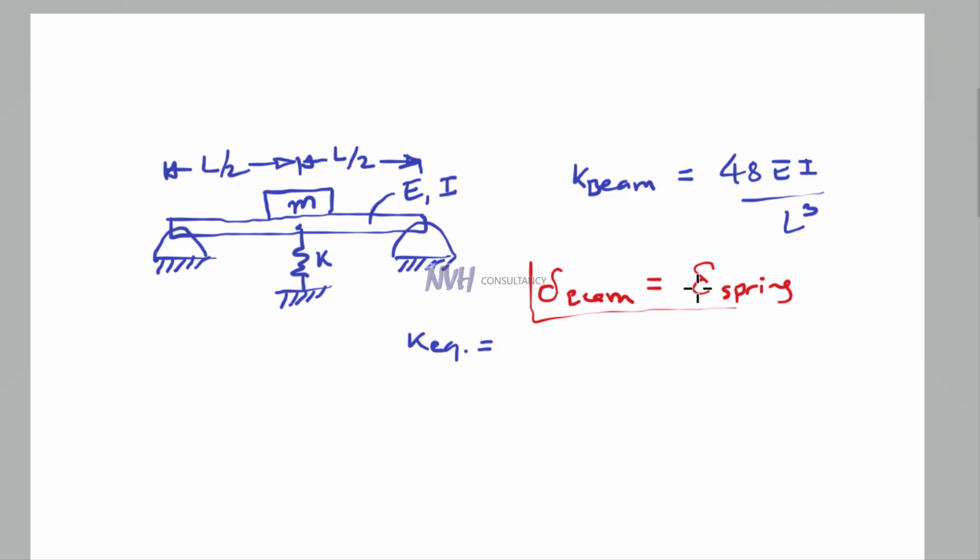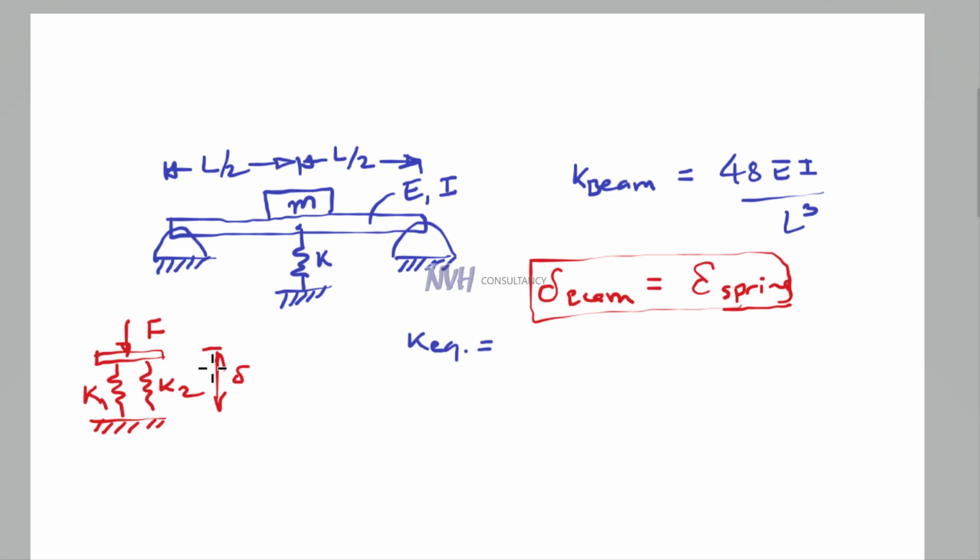So when the deflection is same, then we can safely say that the system of stiffness is basically in a parallel configuration. Okay, so always remember that if you have two springs, okay, so this is K1, this is K2. Now these two springs have one block of mass M and a force is applied, then the deflection of these two springs is always going to be the same.